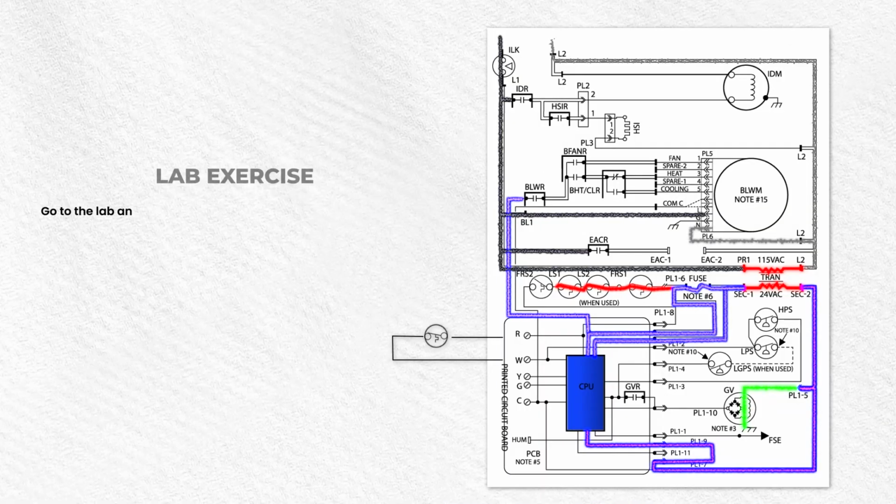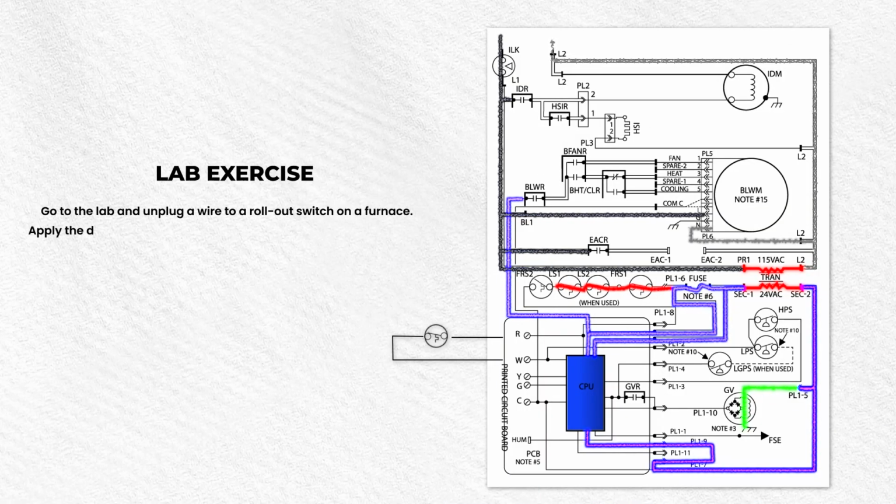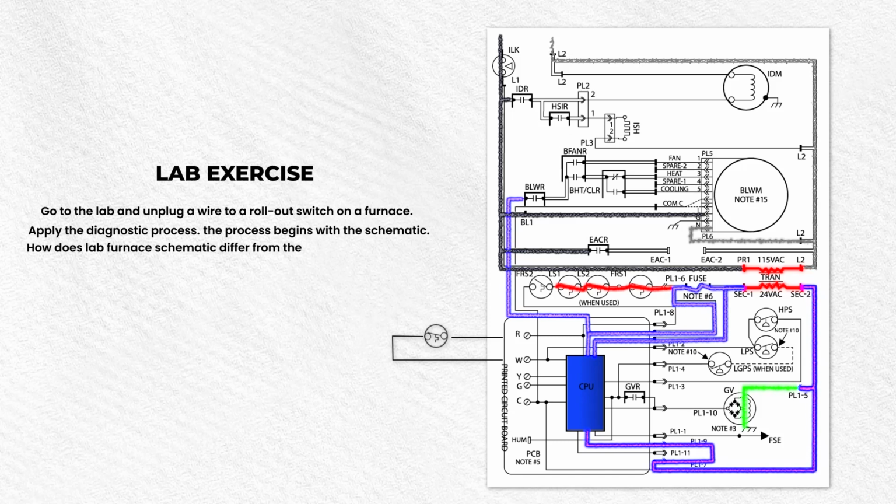Go to the lab and unplug a wire to a rollout switch on a furnace. Apply the diagnostic process. The process begins with the schematic. How does the lab furnace schematic differ from the schematic of the simulator? Document the discrepancies between the fault sequence of operation.